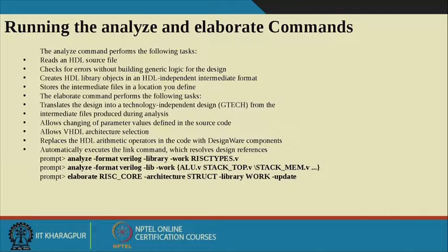If the format is VHDL, at that time you have to write -format vhdl. The library name I mentioned here is work. If you mention another name, you have to mention -library and then the name, then the corresponding Verilog file or VHDL file, whichever you are analyzing.